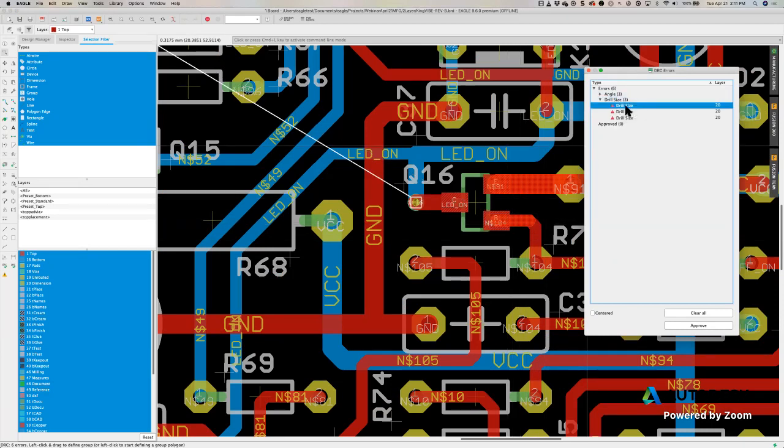We have some drill sizes. The drill sizes is basically just letting you know that these drill sizes are smaller than what you expected to use. Depending on the application, you could go ahead and ignore these, or change this as well if necessary. You could either change your DRC settings, that way you're able to accept smaller drill hole sizes, or actually edit these holes and make these vias with bigger drill hole sizes. So all of these can be ignored. I'm not really concerned about these errors.